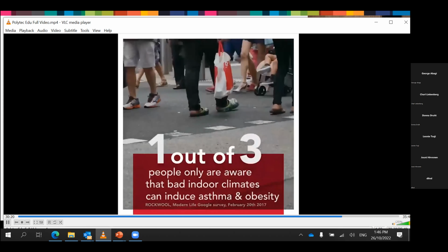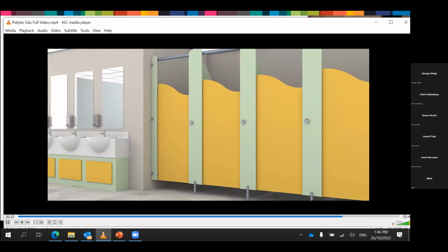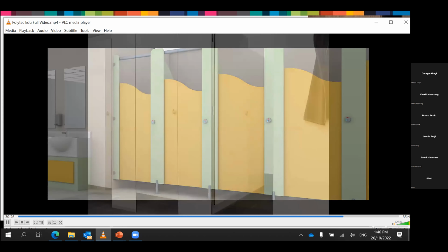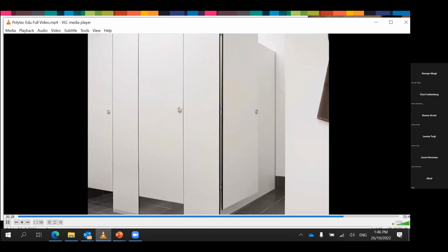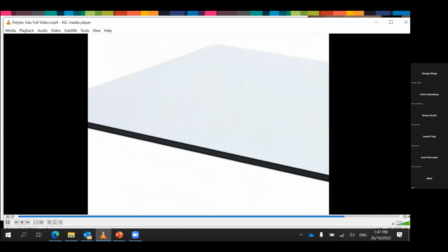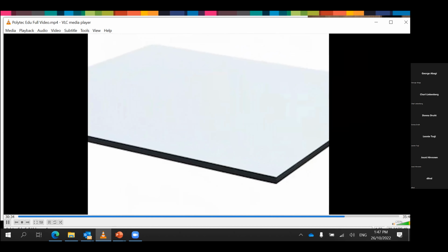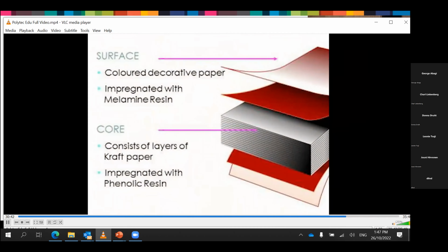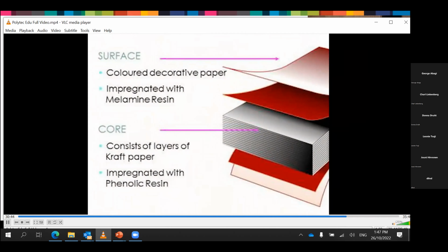How would you select the right system or components for toilet partitions? If it is a high traffic area, then it needs to be highly robust and impact resistant. Typically, 3 material options are available in Australia. The first and most commonly used is compact laminate, otherwise called solid phenolic, of 13mm thickness. The core is generally black and the sheet doesn't require edging.